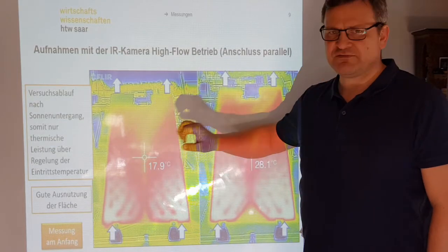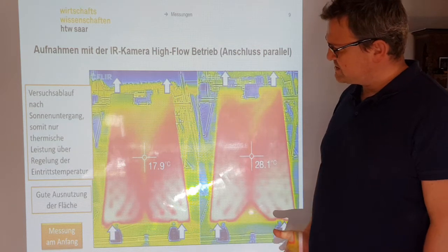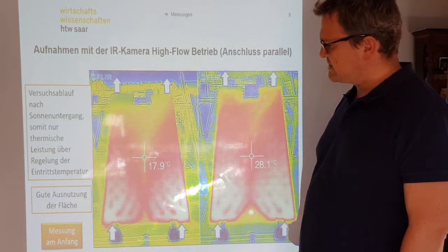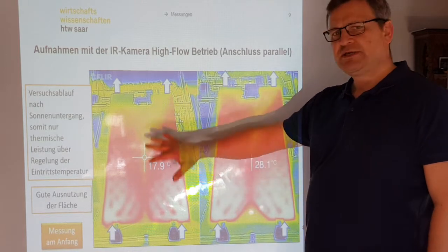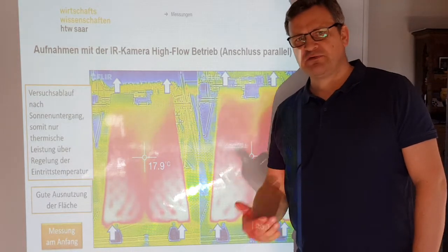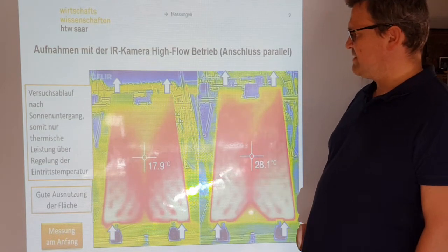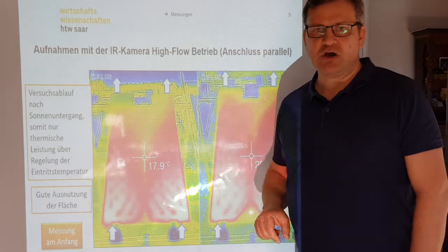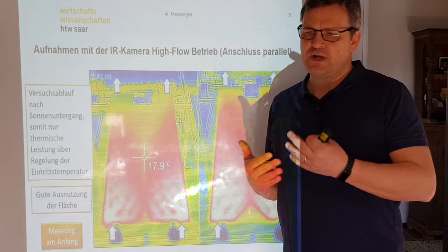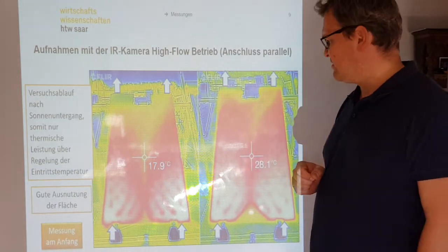evaluate how the fluid flows, and you can do this in this case by filming the heat absorber with an infrared camera. We injected hot water from inside, and the cold water came outside at the top, so we had some impression of how fluid inside this absorber flows.